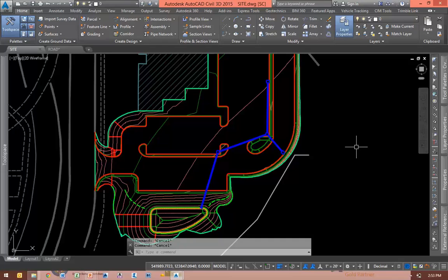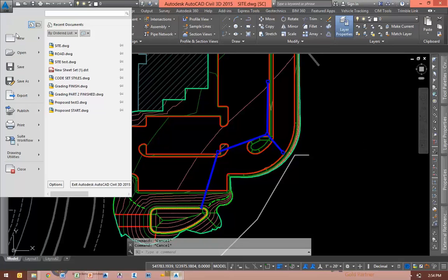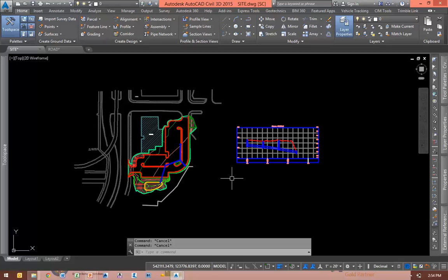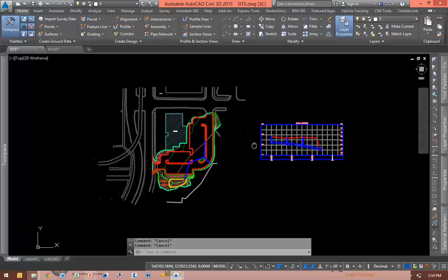I'm going to jump into Civil 3D and show a few routines on this here and a number of different options. We don't exactly have just one workflow to show you here, but rather a few different options. Some of the simplest stuff is to simply take a DWG and export to a DXF. I know a lot of people prefer that because it's really simple. You pretty much hit the Export DXF button. There are some drawbacks to it. You get one file type, it just kind of all dumps into the data collector, and what exports is a little limiting.